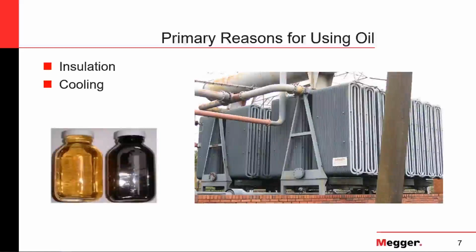So insulating oil, right? And we use insulating oil in electrical equipment for 2 very important reasons. The first one is the oil will serve as an insulating medium inside the equipment, right? As we know, the oil has excellent dielectric properties, and as we also know that the insulation system on a power transformer, for example, will consist of both solid and liquid components. And that brings me to the second important function of the oil inside the equipment, which is cooling.